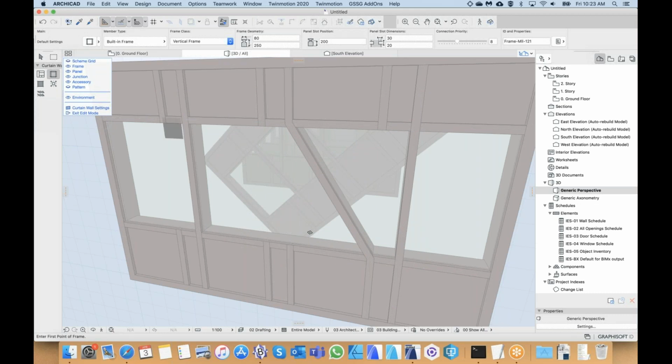If you wanted vertical, so if I just want to connect the dots, I'm going to undo that one. So I'm going to click on one end, and that's a tick. I can always hold shift to constrain to the y-axis, and then move my cursor until it turns into a solid pencil, and then click. When it's a solid pencil, it means that it's connecting to a node.